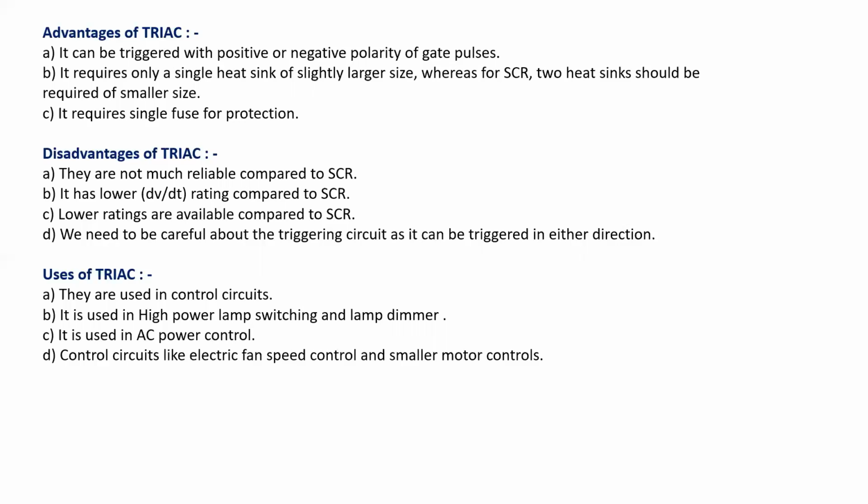The disadvantage is that they are not as reliable as compared to SCR. They have a lower dv/dt rating as compared to SCR. And in the market, they are available at lower ratings as compared to SCR, that is, silicon controlled rectifiers. Also, we have to take care of the triggering circuits for the device.